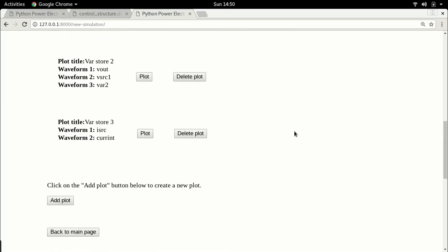So what needs to be taken out from here is that a static variable is extremely important when you want to do control, because in almost all control you will need either a summer like an integral, or you may need the previous value. For example, if you're implementing a low pass filter, a low pass filter will need to store the value of the filter in the previous instant. So you will need x of n and you will need x of n minus 1. That is very common in a low pass filter or many other digital forms of control. So therefore a static variable is very important. So let me just plot it again.